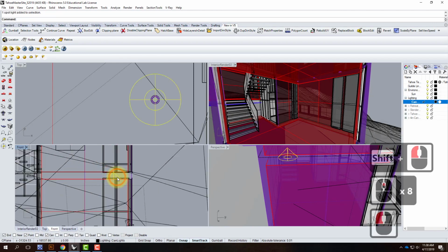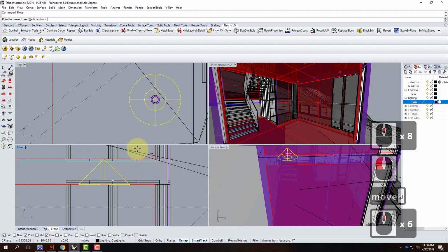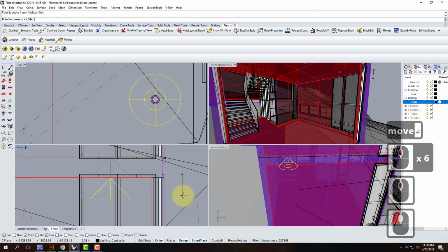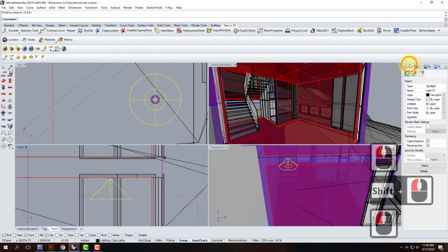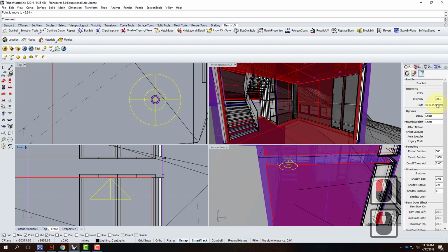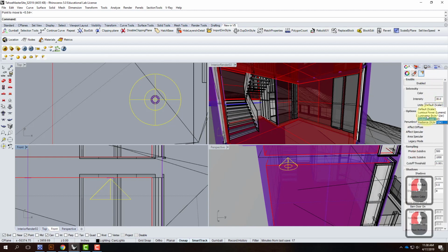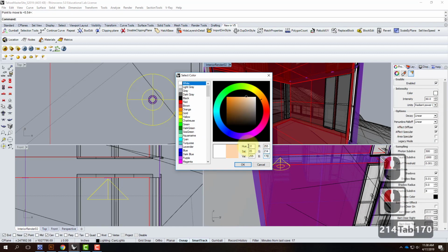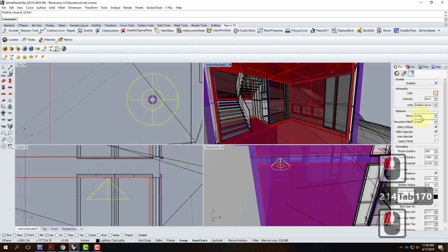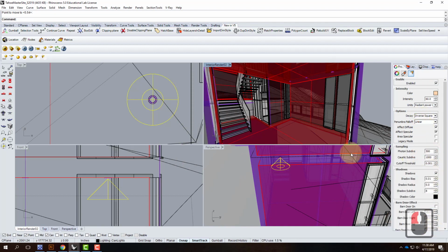And there's my light. Remember that it can't be contained within any object, so we'll make sure that it's lower than my light fixture, something about like that. And then we'll come over to the properties, go into the light, and we have to change our properties. So the units are going to be in watts, and it's going to be maybe a 60 watt. Sorry, I have to move this over. I'm not seeing everything. There it is. Color, 255, 214, and 170. My decay is going to be inverse square. I have numbers here, so it's not a dead bulb, so it should work just fine.